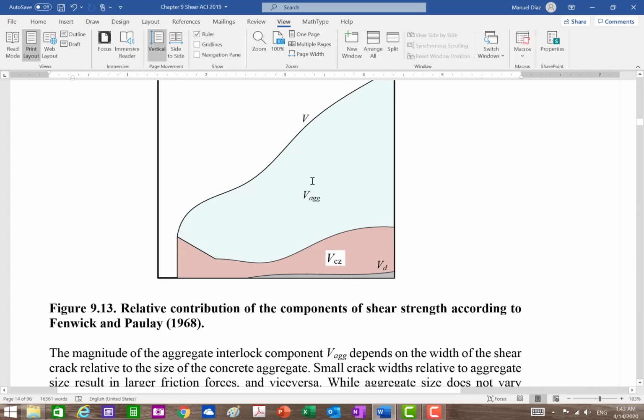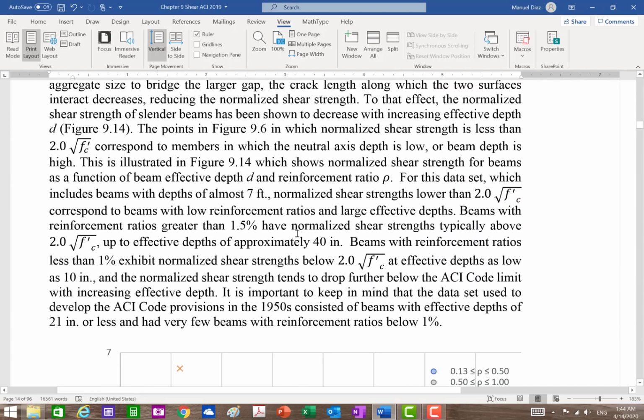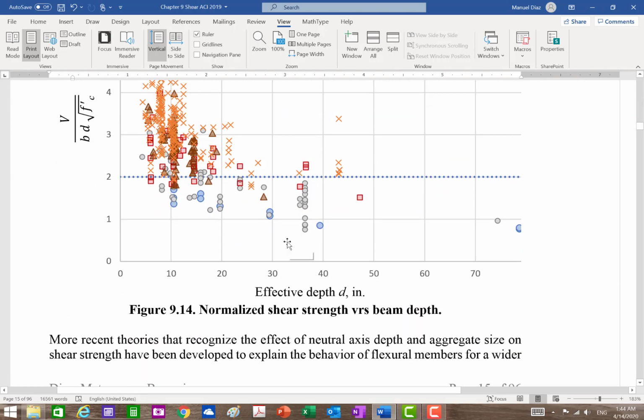This has been changing because with the higher strength concretes, before, the crack would go around the aggregate because the aggregate was stronger than the concrete, right? But now that the concrete is very high, you can crack the aggregate and you can go through. So then this is being reduced as you increase your concrete strength. Okay, so that's all you want to know there. No more. Forget about this.